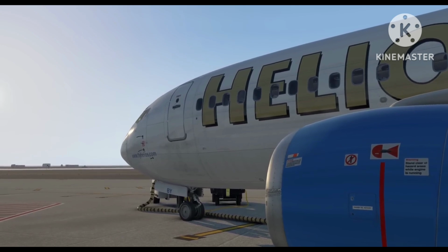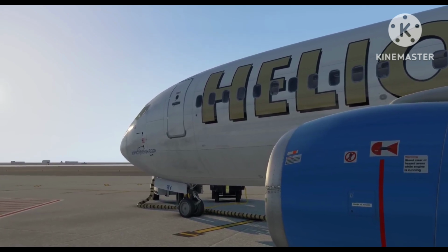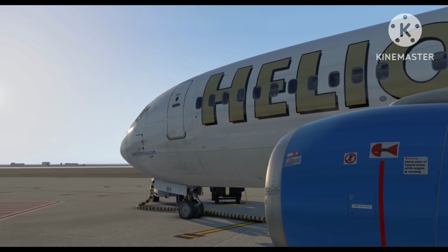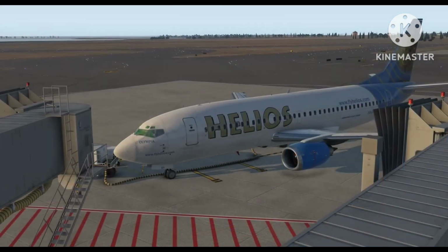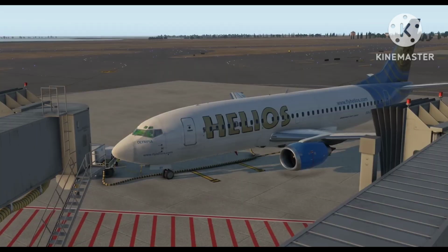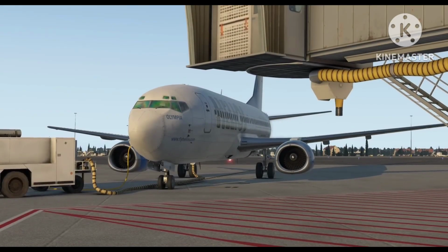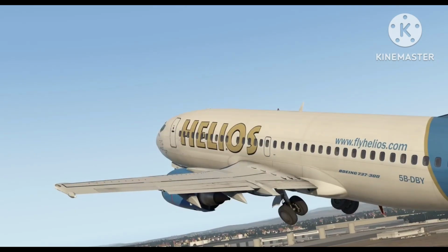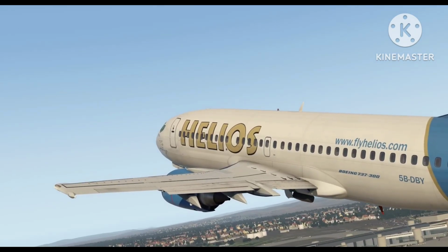When set to auto, the system automatically controls the cabin pressure, ensuring it remains at safe levels as the plane ascends or descends. However, if the switch is mistakenly left in the manual position, the automatic control is disabled and the pressure must be manually regulated, which is typically only done during maintenance checks.